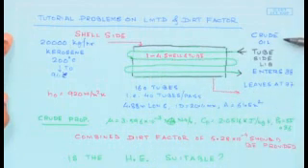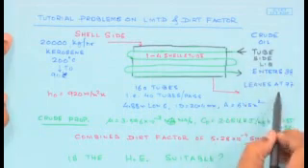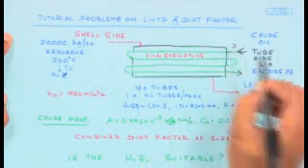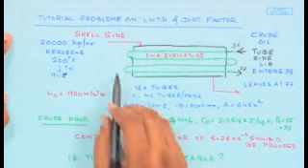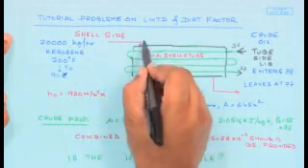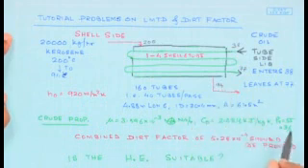On the tube side, we have crude oil, which enters at 38 degree centigrade and leaves at 77 degree centigrade. So, this is 38, it leaves at 77, and the shell side is at 200 and it leaves at 94.